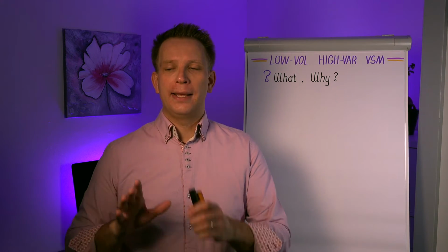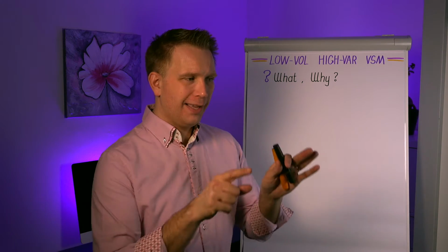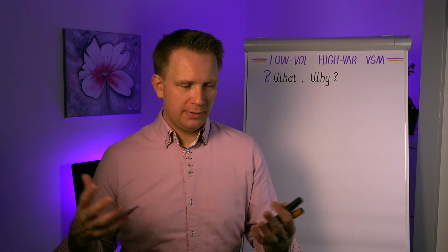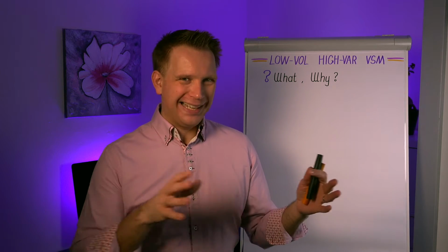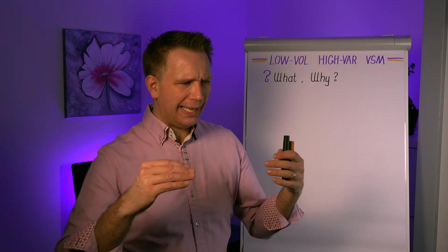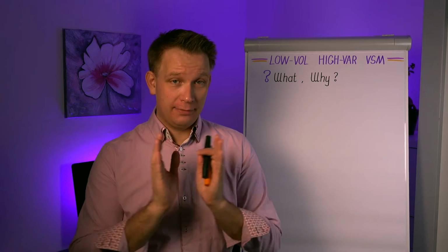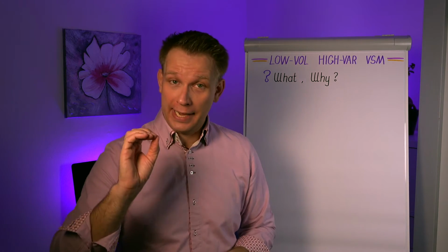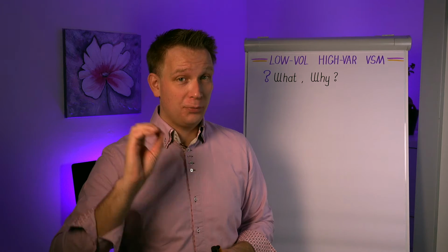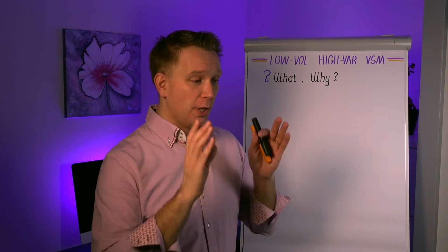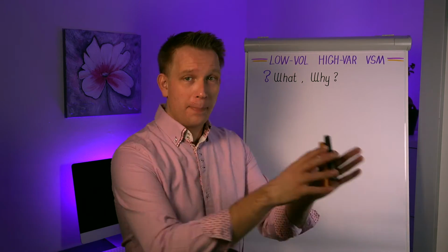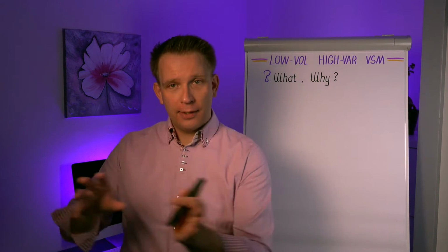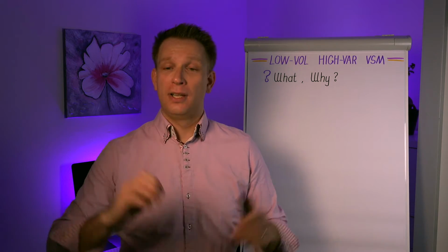Also know that the traditional way of counting work in progress, WIP, counting that in between the processes, is something I would really advise you to do for a high volume, low variation production. Just walk the process from the end all the way upstream to the front of the process and physically count how much is there today.